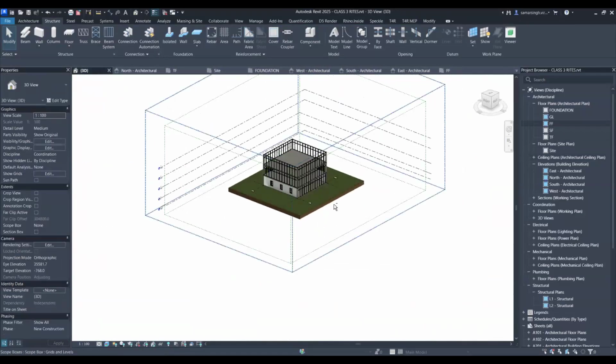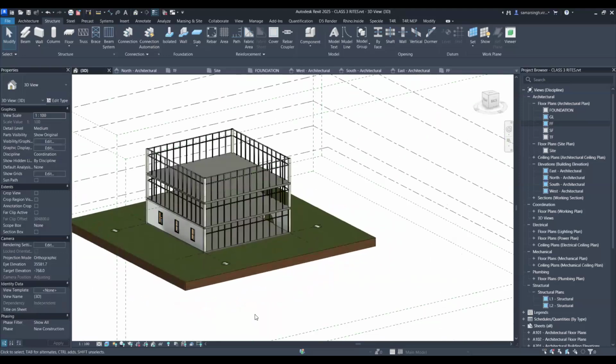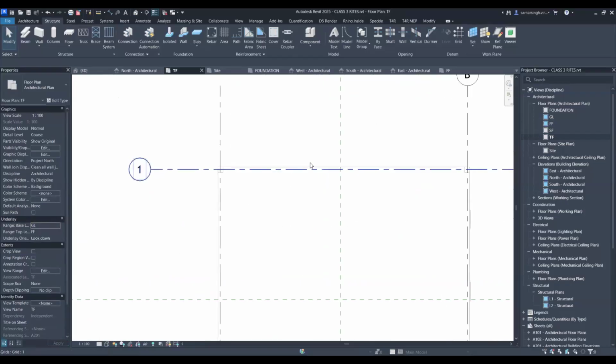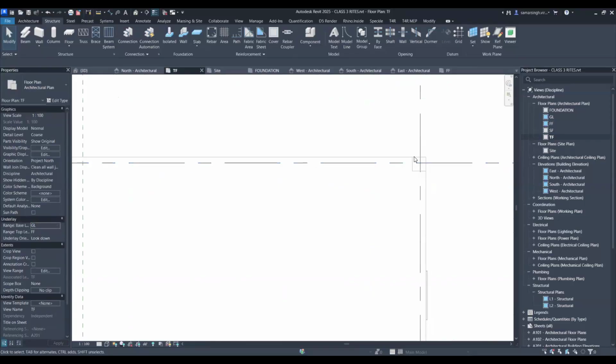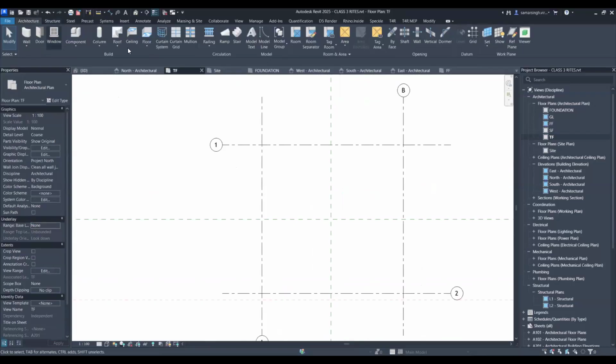All right. So this is our structure. Now let me just go to the third floor and here let's just create a roof. But to create that footprint, I would actually want to see what is below. So I will go ahead and choose ground level, apply. And here you can see that this is almost the case. So I can take the offset from the structure grid as well. So I will just turn it off. Then I can go to roof.